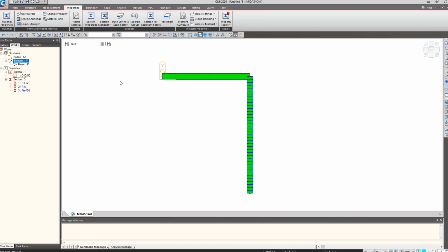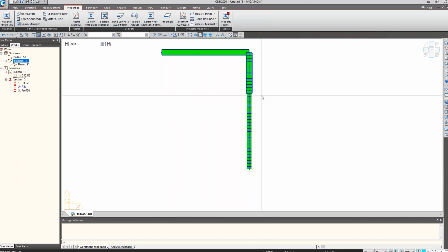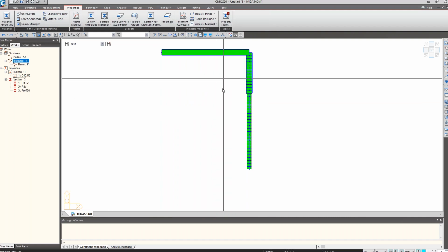that were here. And then we need to understand at which point this is an abutment wall and at which point is a pile. That happens at this node here. So we're going to select all the beam elements below this point. They're going to be pile 750, and all these sections here are going to be our 1 by 1 section.